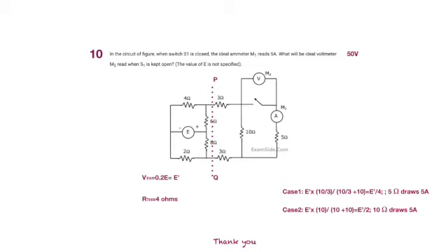And the Thevenin's resistance, when you look back, because the source is shorted, that is E is shorted, we see that now we are having 6 and 4 in parallel through the short, that is 2.4, and 8 and 2 in parallel, that is 16 by 10, 1.6. So 2.4 plus 1.6, 4 ohms. Now the left side has been completely resolved into a very useful concept of a Thevenin's, wherein we are having 0.2 E as E dash, I'm just calling it E dash for the time being, and there is a resistor 4 ohms in series with it, a Thevenin's equivalent.